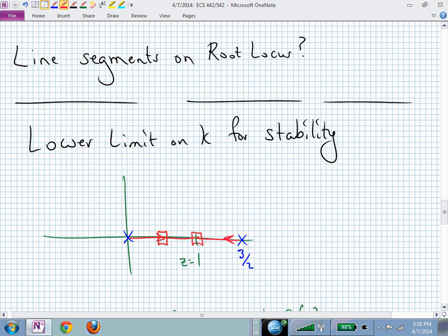And we have one at z equal to 1, and the other one we didn't know where it was until we fixed k equal to 1/2, and then we found it. We said, oh, we're actually going exactly the same distance as we crank up the gain k. And that's not always the case. But in this case, with 2 poles and nothing else, they're moving at the same rate towards each other.